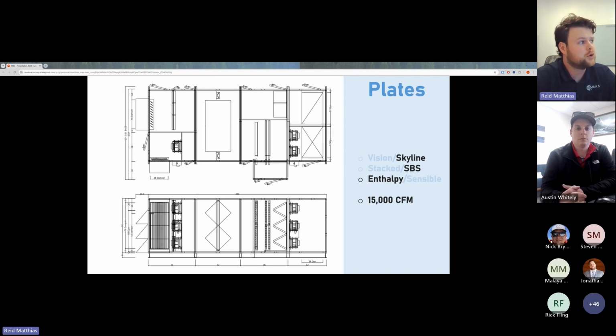So we're taking a Daikin Skyline unit and building inside of it. We're putting foam injected paneling down the middle of this unit, basically saying the filters need to be at 500 feet per minute. On the other side of those filters is just a fan that can squeeze up a little bit more as far as the velocity goes. That way we can make this unit as narrow as possible.